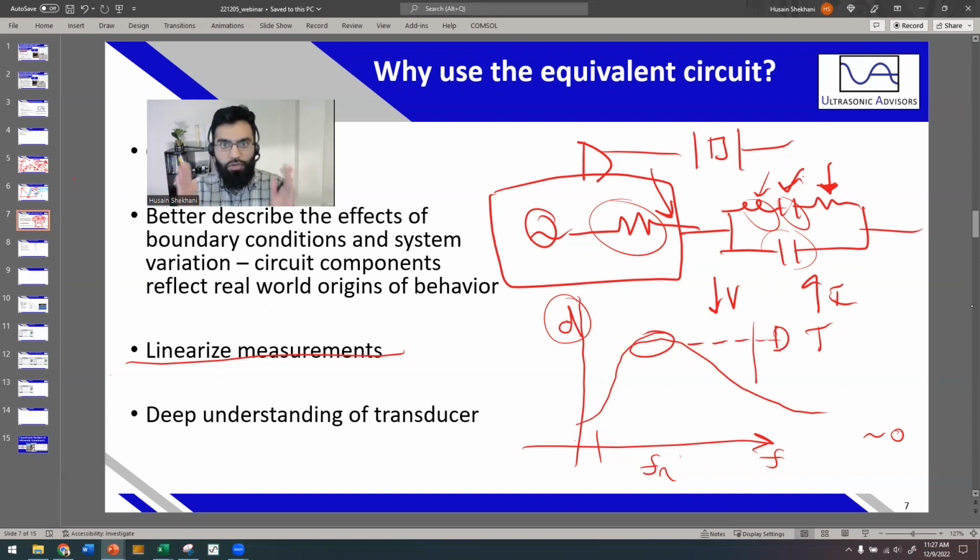So basically, we can use the equivalent circuit to narrow in on a specific region where we have linear behavior and extrapolate more properties, versus doing incorrect analysis from a 100-voltage sweep across a transducer, comparing apples and oranges to calculate properties. It's not a good thing to do. Friends don't let friends do linear analysis on nonlinear systems, unless they can find a small region where there's linearity.